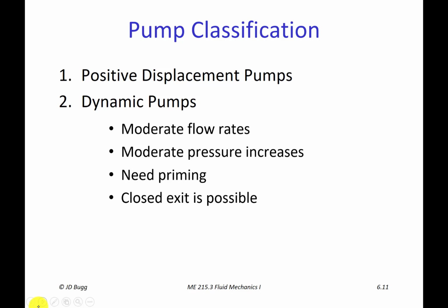A nice feature of dynamic pumps is that the exit can be closed, and unless we leave it closed for a long time, there's not going to be any damage to the pump. We'll see why that is when we look at the detailed construction of the inside of dynamic pumps. And these are by far the most common type of pump, particularly centrifugal or radial flow pumps, which is where we'll be spending most of our time.